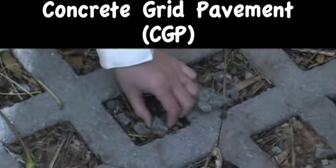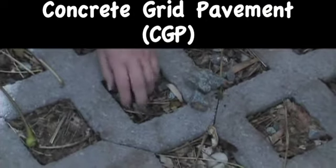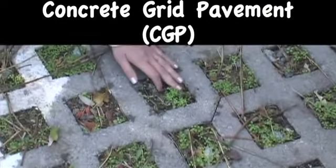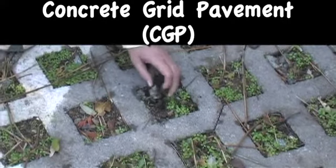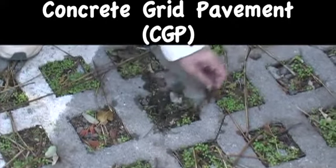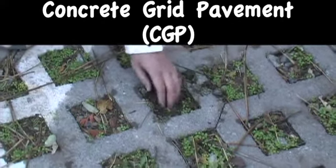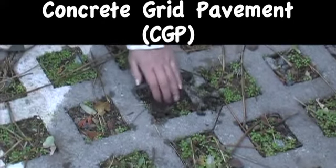The third type of permeable paver is the concrete grid pavement, or CGP. CGP is an extensive concrete grid unit that uses large spaces filled with stone aggregate or sod. The reinforced concrete structure provides stability for vehicle traffic, and the gravel or sod-filled spaces provide permeability. A feature unique to this paver is that vegetation is allowed to grow within the structure. The benefits are both environmental and aesthetic.